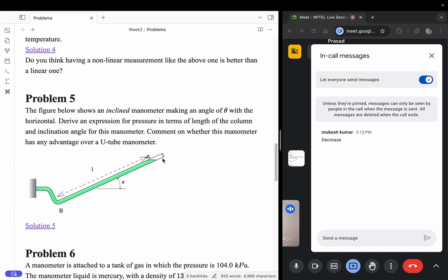This is purely because of gravity, since gravity acts in the downward direction. Even though there is this much fluid on top of this, gravity is acting vertically downwards. If gravity acts downwards, then you will feel force only in the downward direction, not along the length. So though there is L length of fluid, it is not directly on top of you but at a certain angle. You have to accommodate that angle and then calculate your hydrostatic pressure, right?